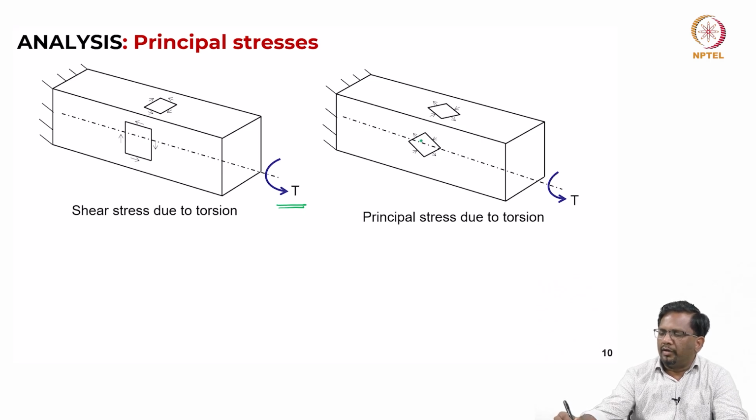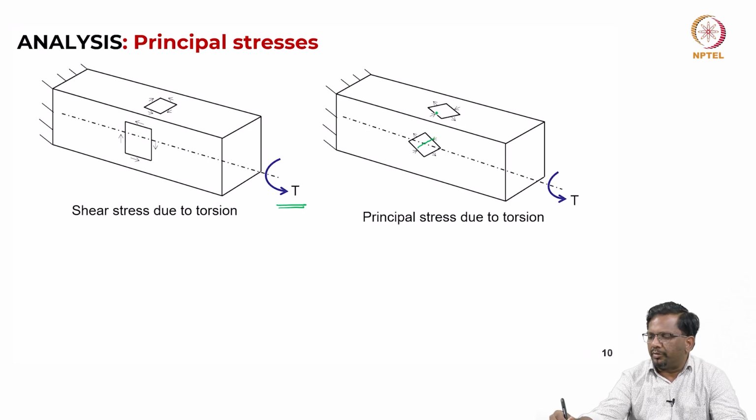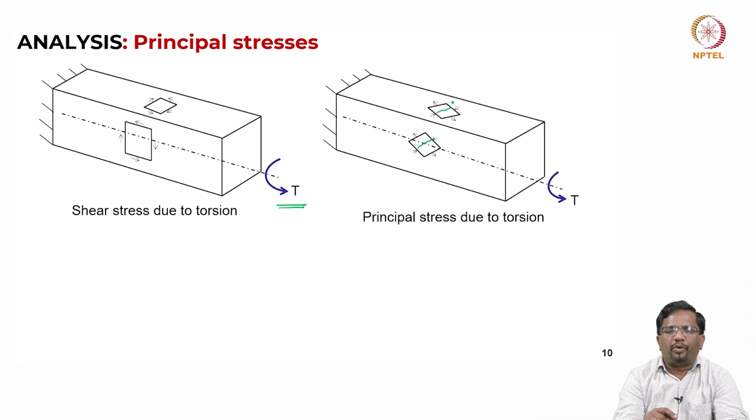The crack is going to follow the principal compressive stress direction, because the cracking will form perpendicular to tension. We have seen that, right. So, in this case it is going to be like this. Depending upon the nature of your stress distribution, I can convert it from Mohr circle, again we can convert it into principal stresses.